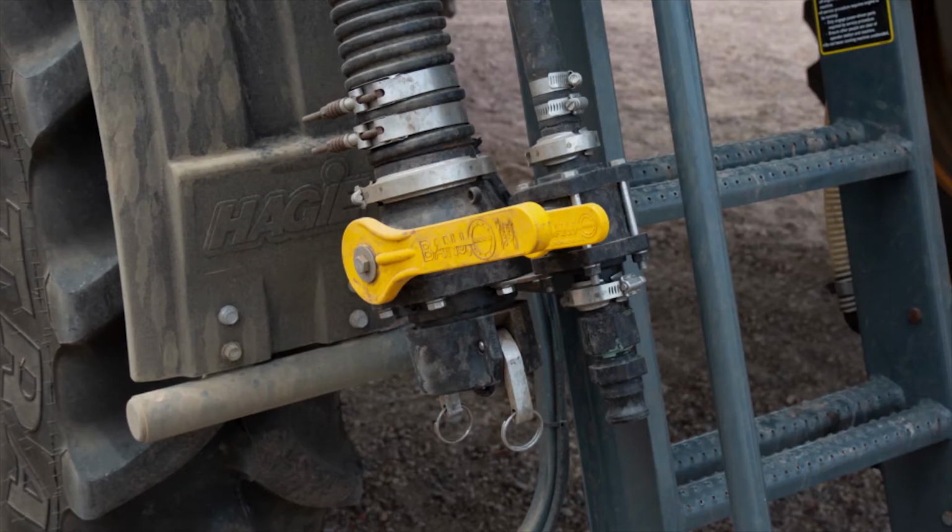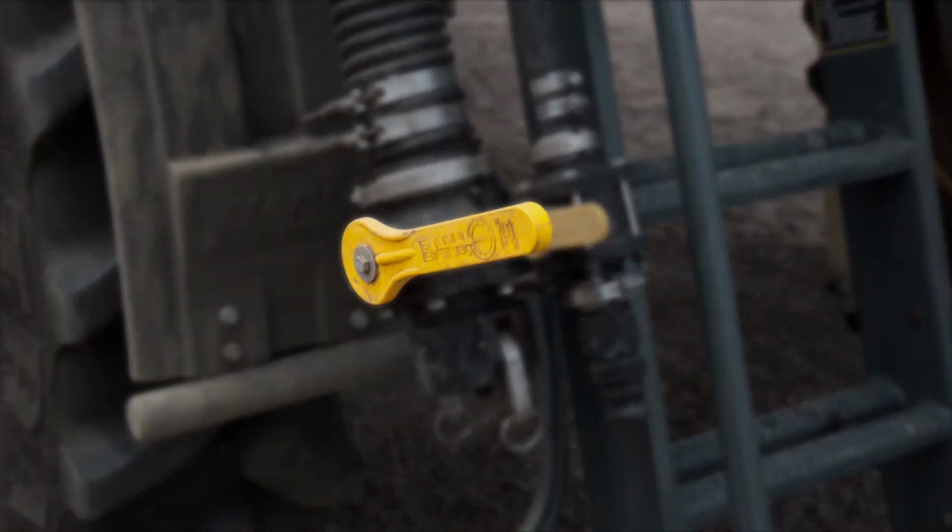When we look at fill options on our Hagie machines, this is a rear fill option that we're looking at. The rear fill option is positioned right by the rear ladder where we access the operator's platform and get up into the cab, which is the gray portion kind of to the right there. The rear fill option locates our solution line and our clean water rinse line right to the back of the machine. The one on the left is our 3-inch fill line that goes directly to our solution tank. The one on the right is a 1-inch line that goes to our rinse water tank.